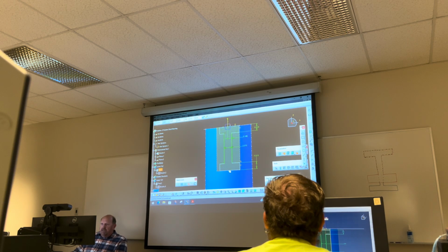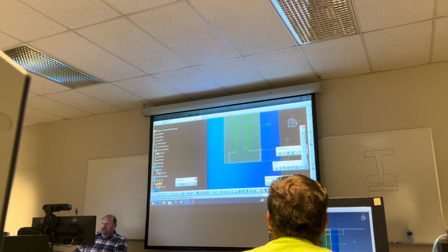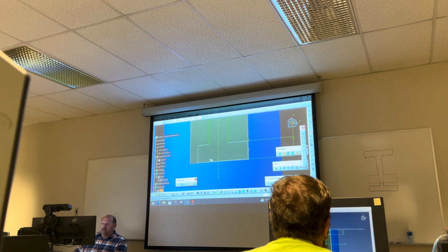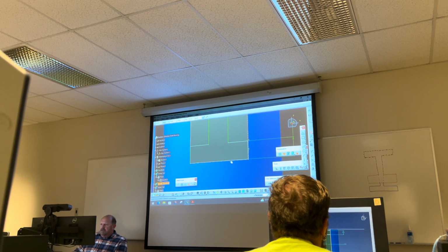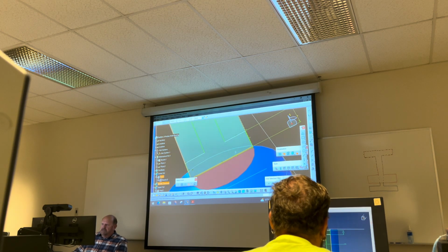I'm not gonna put a total length on this. I do know it's 2 inches, but rather than do that, if you look, I'm off a little bit on this part. I'm gonna come back in here to the constraints command, and I'm gonna say I wanna take this one over to this, and I wanna make it coincident, okay? And it goes green. I'm gonna take this one, and I'm gonna bring it down to this reference line. I'm gonna say coincident. Pick that up.